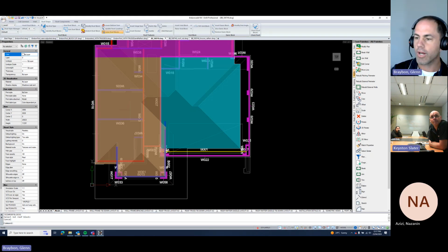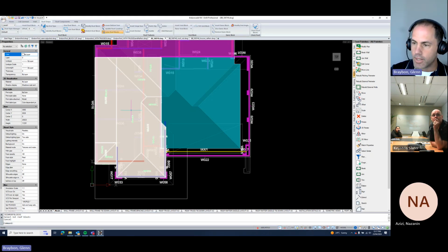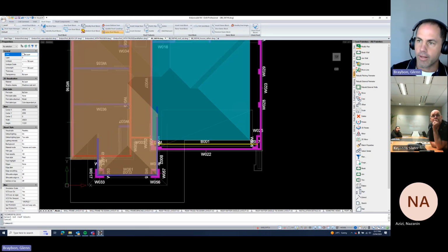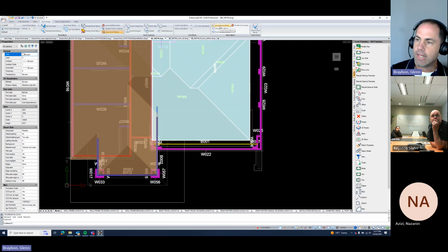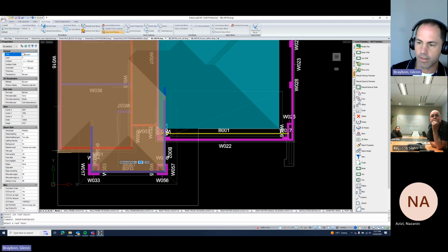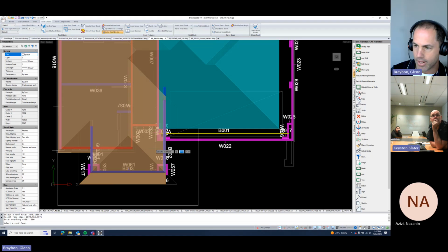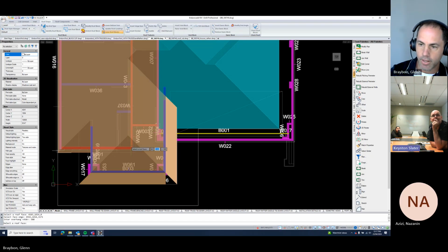Right. Cool. Okay. So now I've got this funky looking roof block here, and just to show you, obviously the eaves. We're going to insert an eaves block. Select the roof face, select the edge. Then I think 500 is where you guys are at. Maybe, anyway, doesn't matter for this one. Go 500. Yeah, looks like it.